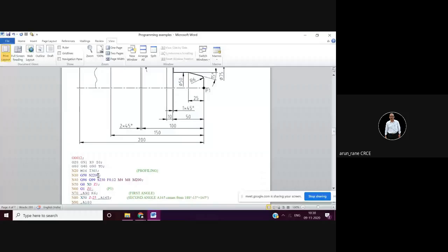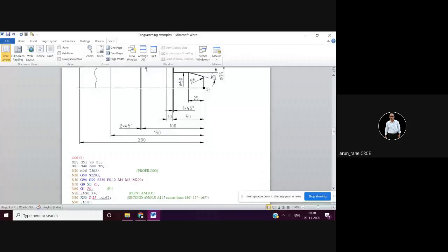You can have T0, you can have T03 like this. So you can write T0305. Nobody does it like this, because this means tool number 3 and it will read the offset from row 5, which is actually confusing. So you may make mistakes. So it is always better to avoid this. Or you can use the offset form.